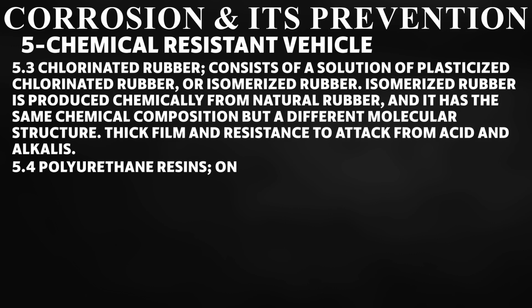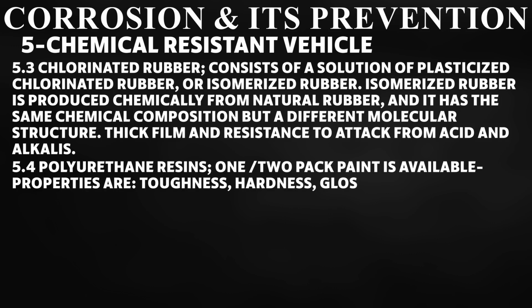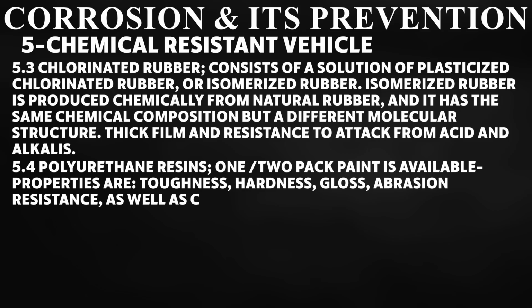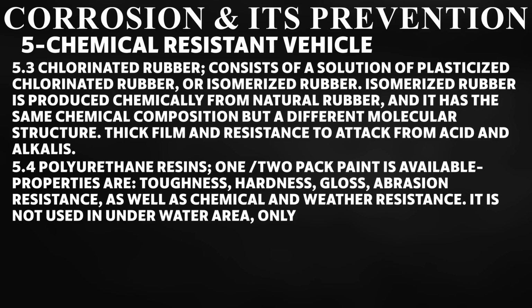5.4 Polyurethane resins. One or two pack paint is available. Properties are toughness, hardness, gloss, abrasion resistance, as well as chemical and weather resistance. It is not used in underwater areas, only used on the superstructure.